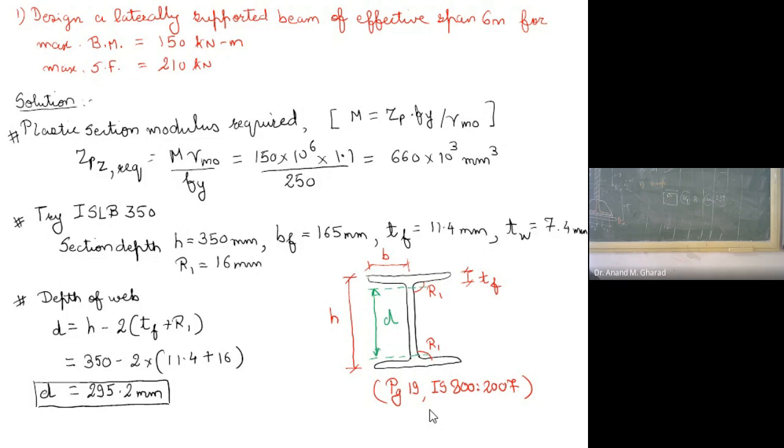Okay. Now with all this theoretical concept and whatever explanation I have told you, there are a few things we need to remember: whatever design we are doing for a beam, especially for steel structure, it should be in the compact or plastic zone firstly, that is, local buckling should be taken care of, and second, the complete beam we are designing should be restricted in the lateral direction. If not, then we are supposed to make certain provisions. That we call the laterally restrained and unrestrained case. So we will be discussing and designing both these cases, and let us try to understand how the process is.